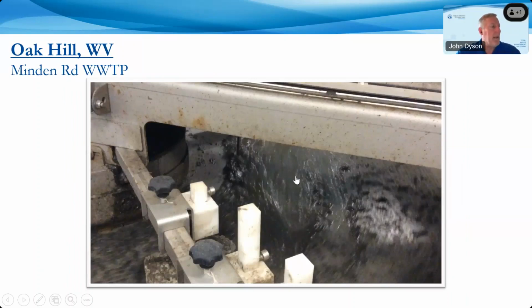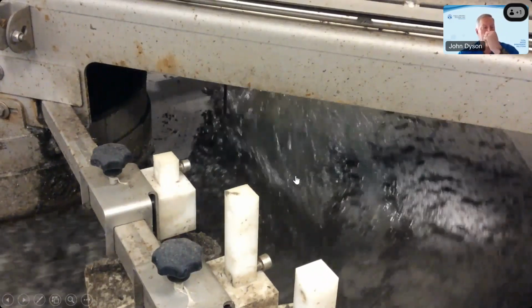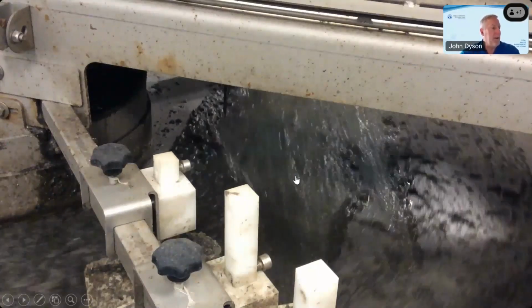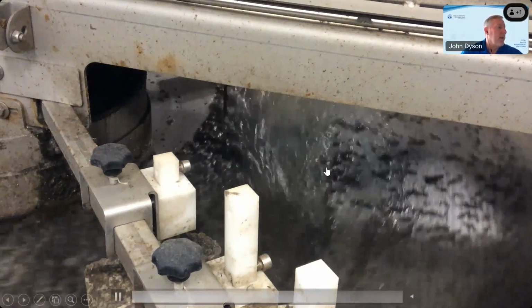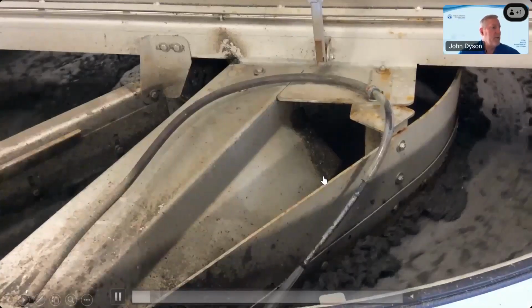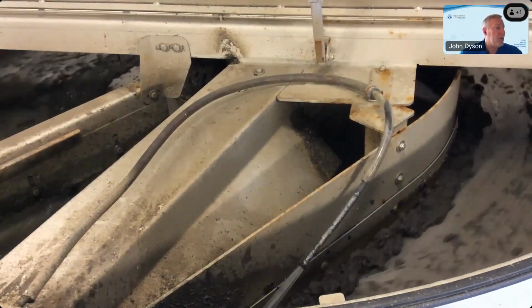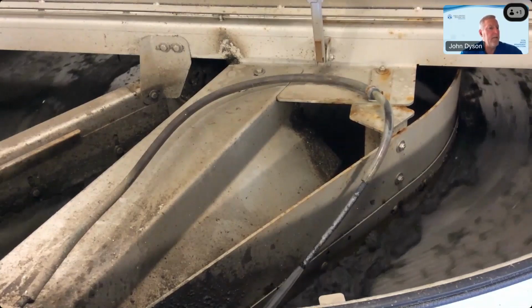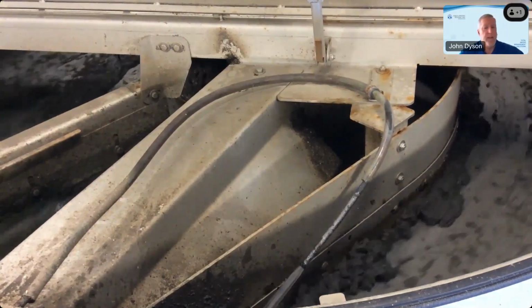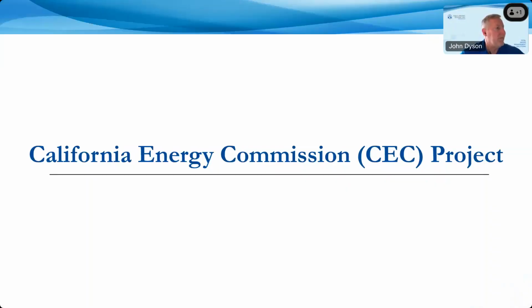Another question a lot of people ask is the sludge, and what do you do with it? In the case here, they do mechanical thickening, so they take the 2 waste flows, add polymer, and you can see going onto the system, it's very efficiently dewatering out. You can see this is the other side after it's just come around, and it's getting really thick. So they get about 10 to 15% concentration very easily, and they mix that with their waste activated, aerobically digested, and that gets fed directly to their final dewatering at their facility.